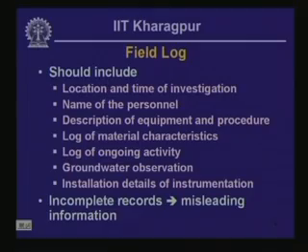The second thing that must be included on the field log is the name of the person who is logging, as well as the name of the driller, because if the designer needs some information regarding activities which are not appropriately mentioned on the field log, which are missed out from the field log, in that case the personnel who signs off the field log, they can be contacted.